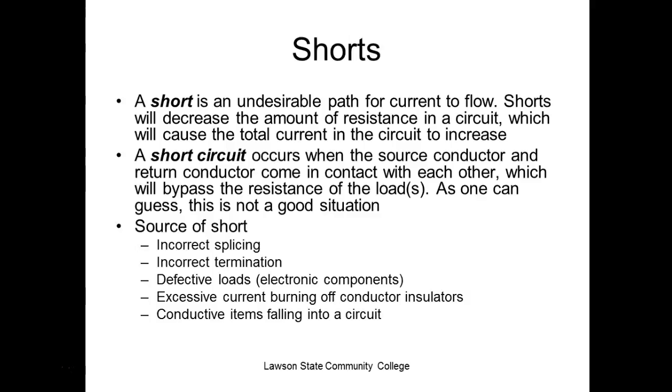Now, what that means is that once we get a short, one of the big things is a short will always cause the opposition in the circuit to go down. And when the opposition goes down, the current goes up. We've got another term called a short circuit. So we can have shorts and not have short circuits.